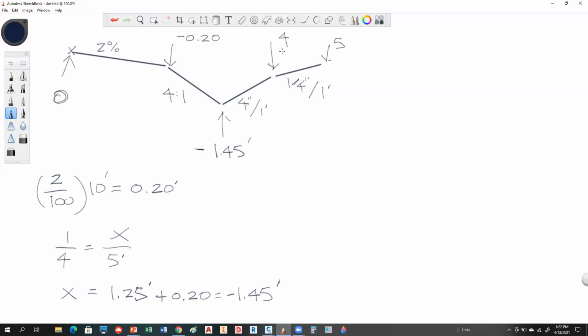And what that's going to do for us, though, is give us reference back to here. See, the whole idea is you want to make this simple. This is the number you're going to know right here. See, the profile says, okay, if I want to put the ditch in, all I need to do is take the profile centerline elevation and subtract 1.45. If I want to do the face of the sidewalk, I just take that elevation and add or subtract whatever that number is. Do you see what I'm getting at here?